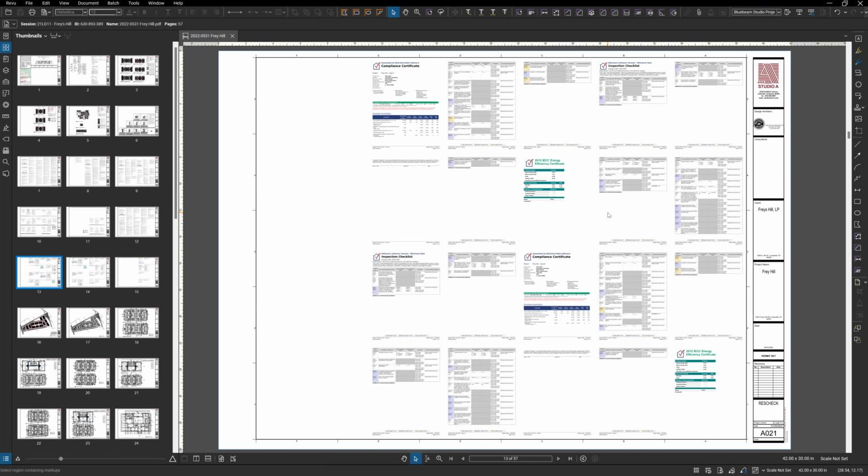is something that you are allowed to do for any building that's 3 stories or less in multifamily, and is typically less strict than a Comcheck. Com standing for commercial building. I want to make it plain, and this is where people get confused. They see Rescheck and they think residential, and then they start to think that these buildings are governed by the residential code. They are not governed by the residential code. We're governed by the commercial code, the International Building Code.